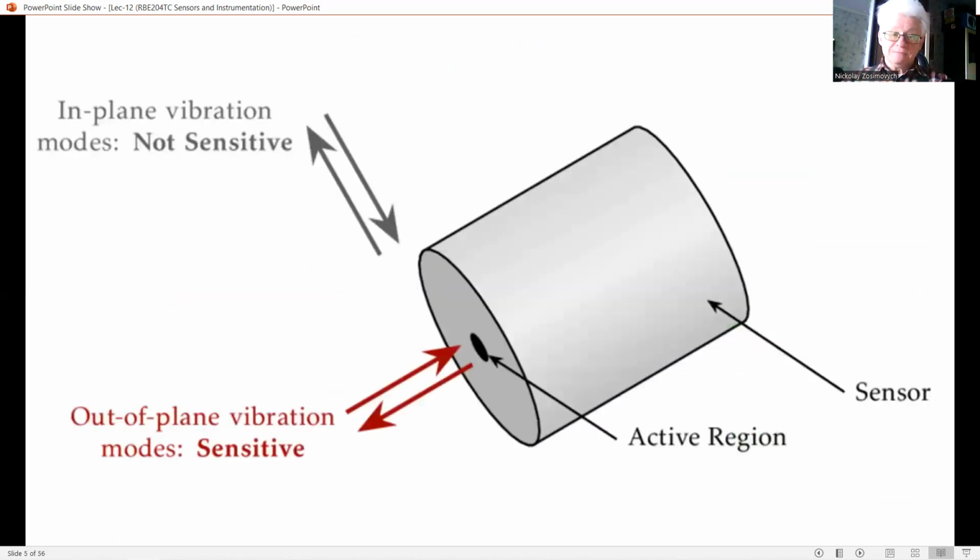Piezoelectric sensors have disadvantages too. The surface charge produced by an applied force might be neutralized easily by charges from the environment, sometimes called airborne charges, by current leakage due to a non-zero conductivity of the dielectric, or just by the input resistance of the connected electronics.